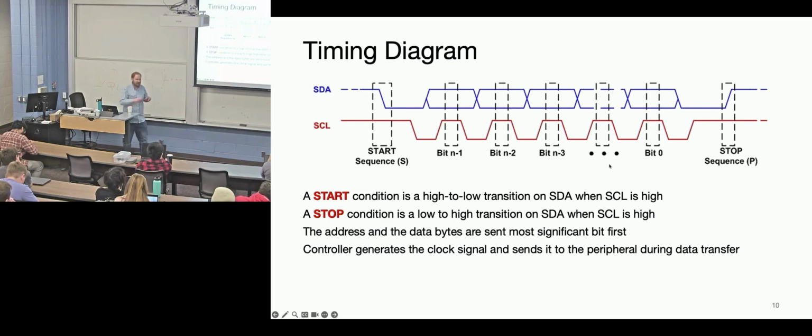This also makes a little bit of sense if you think about the clock having this RC charge up and discharge cycle, and in practicality you have these little spikes that are going to happen inside your data bits. It also means that your peripheral or your device has to be a little bit more sophisticated in its timing, because it has to on its own know when to transition between the data edges.